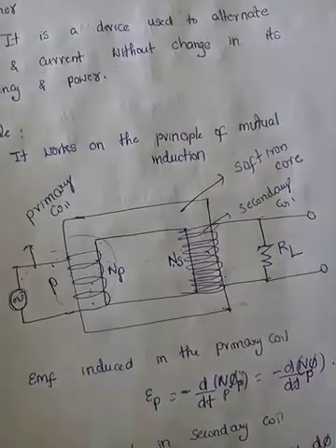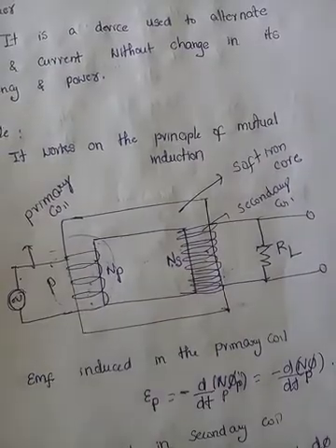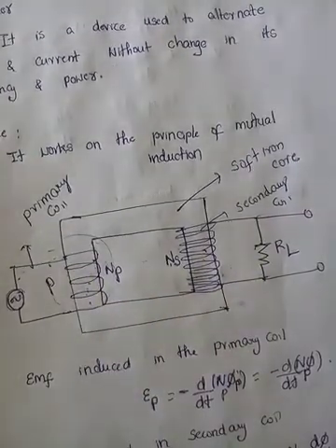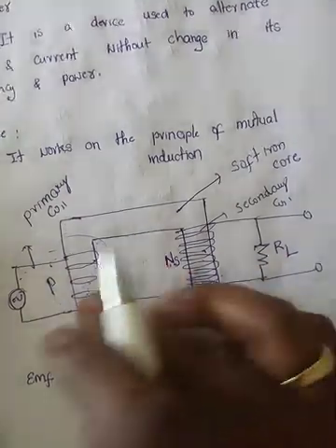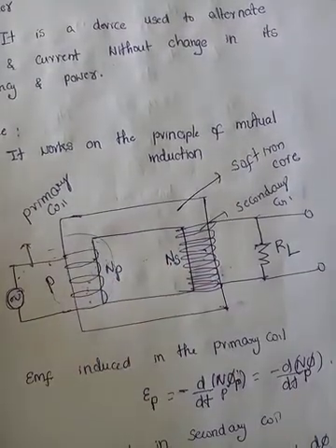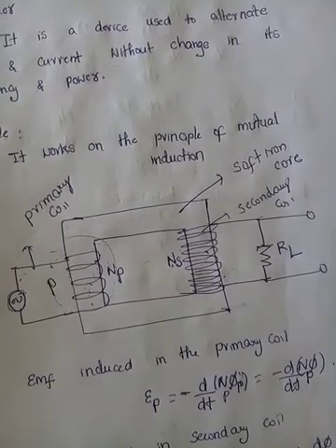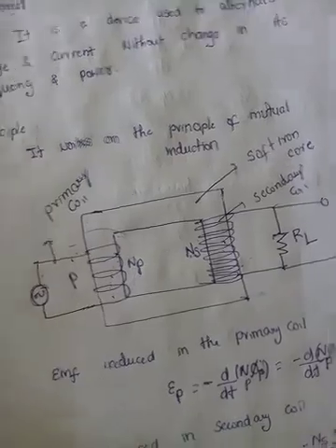We consider the ideal condition, but generally there is some flux leakage. Now, to avoid this, what will we do? We wind two coils on the same core, like the mutual induction of two coaxial solenoids we have done. On the same core we place both coils, insulated. So the gap is very small. What happens then? The flux leakage can be reduced.